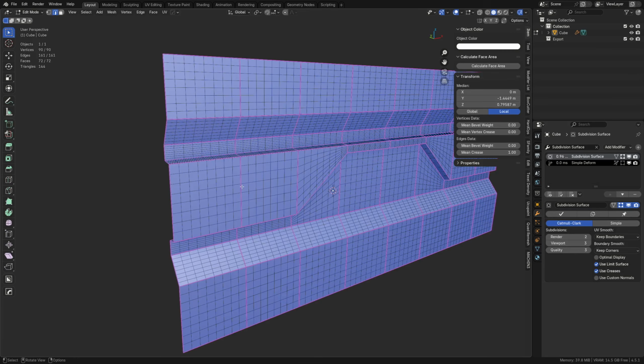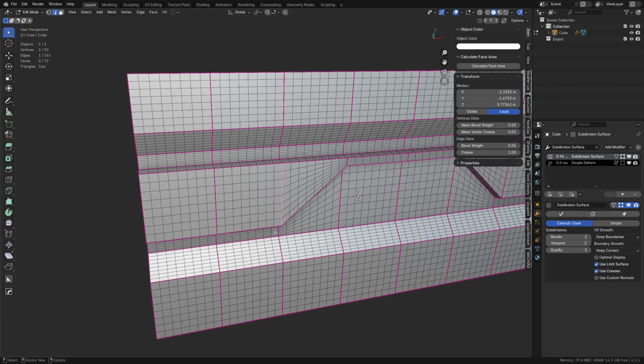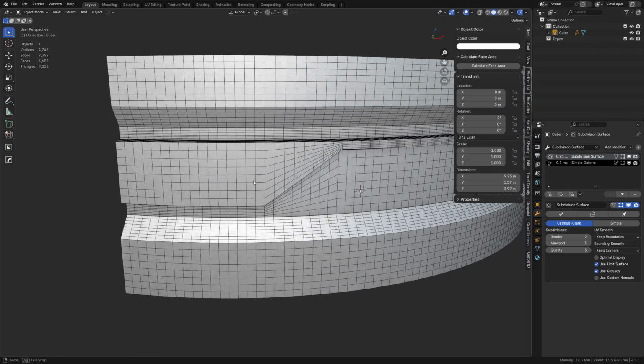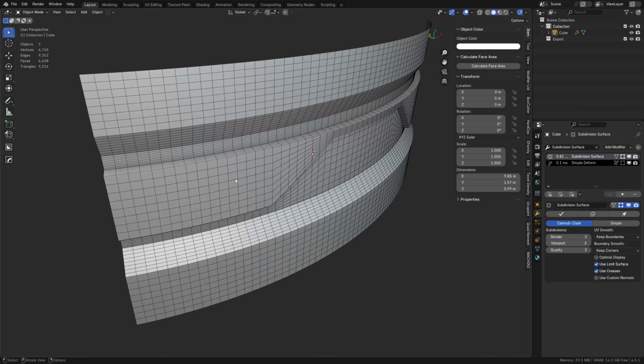You have to crease these mid edges here, which the turbo smooth setup doesn't really do. But you have to do that. What this does is it allows you to control the edge flows a lot more precisely. Now, because what's going on is that the bend is controlling the curve, it doesn't really care about the top of it that much. We just get higher resolution.